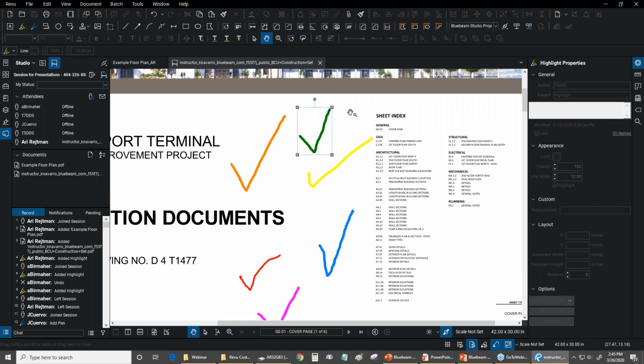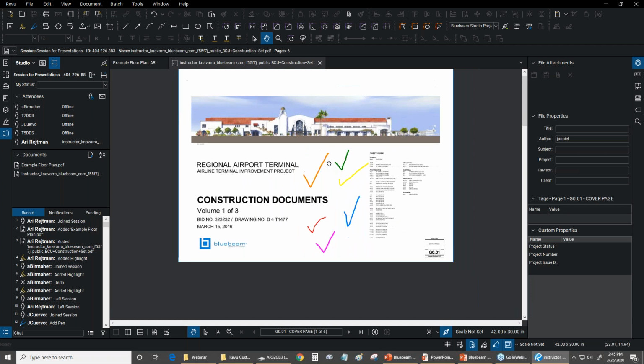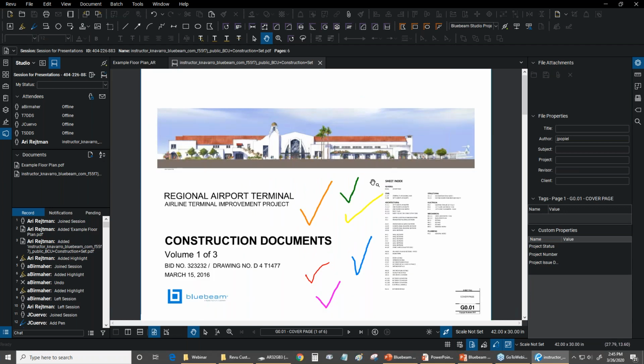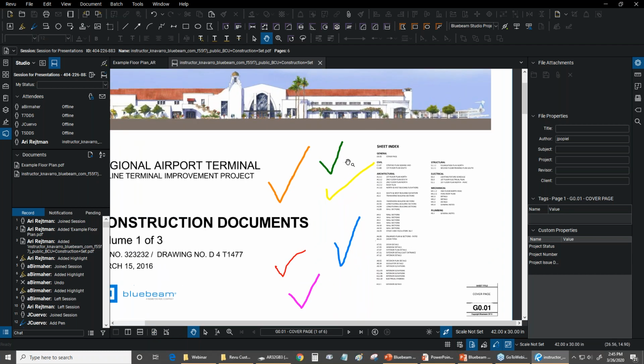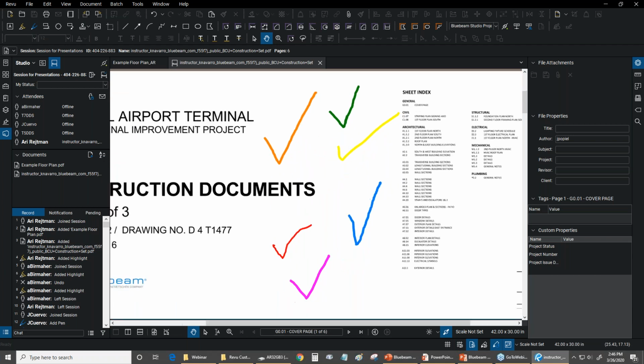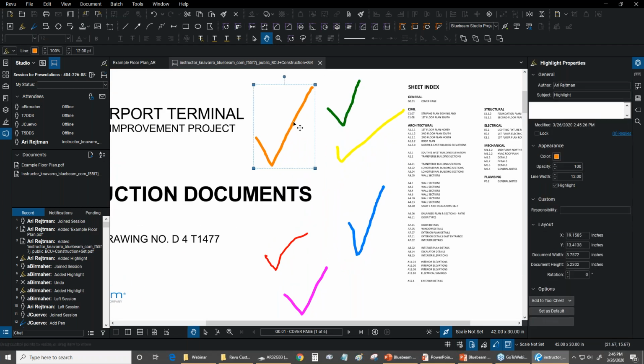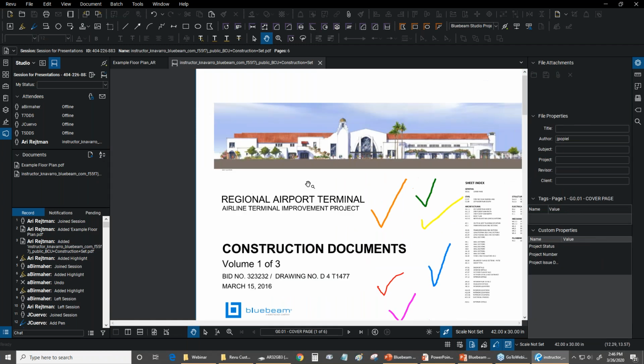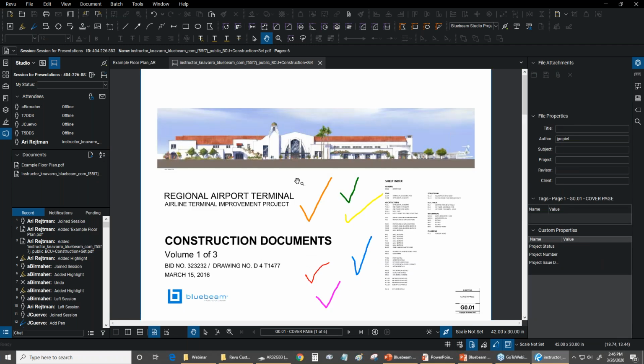So my colleague can draw markups offline. Especially in the construction field, if you're going onto the field and bringing your PDFs with you on a Surface Pro or even an iPad, for example, you can manipulate your markups there. You don't have to be using the internet. You're going to see a bunch of red dots next to all of your markups, and they're going to stay there until you connect to the internet. That red dot is a small red circle with a cloud on it. It means you're not connected to the cloud, your markups are local, and you still don't have to worry about saving.